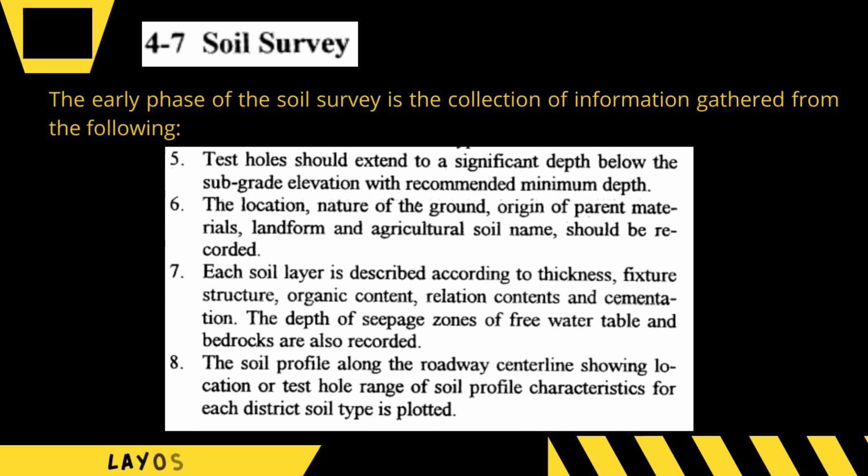Fifth, these holes should extend to a significant depth below the subgrade elevation with a recommended minimum depth. Next, the location, nature of the ground, origin of the parent materials, landform and agricultural soil name should be recorded.